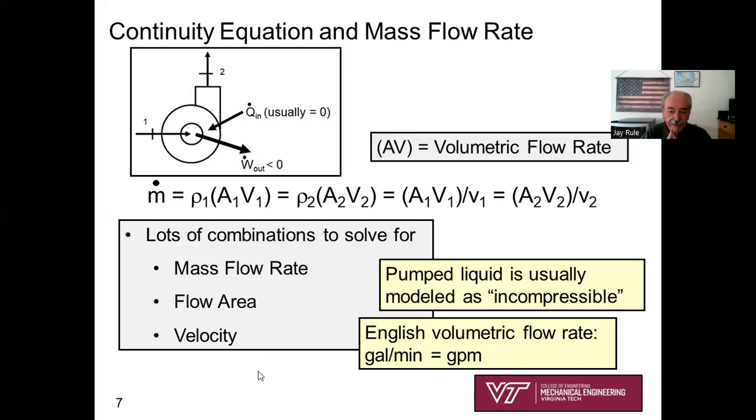And so that can give you some clues in problem solving as well. And a lot of times when you're given a number of variables, you're always trying to find that third variable. In an awful lot of your engineering problems, you're given the volumetric flow rate of a pumped liquid. You look up the specific volume or density, and then you determine the mass flow rate.